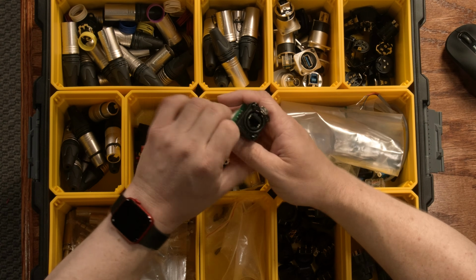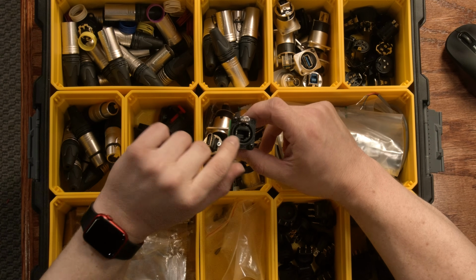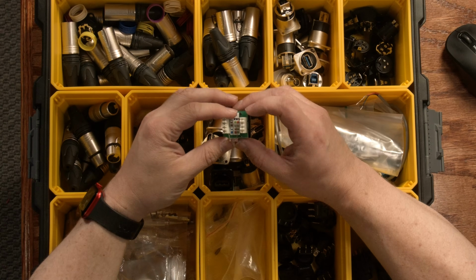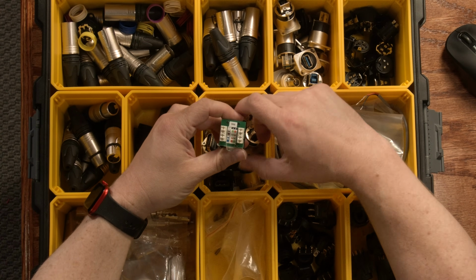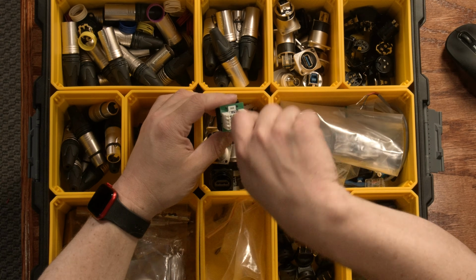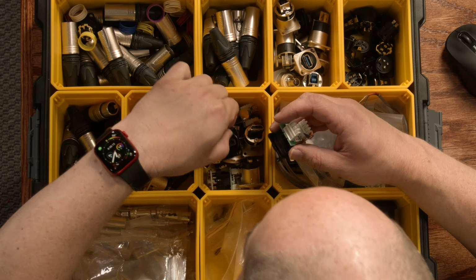Another one that I use a lot is EtherCon, so that's actually an RJ45 for doing Ethernet. And they have a lot of different variations and versions of these too. This is a punch down on the back, so you use a punch down tool to punch it like you would on a patch panel. But they also have feed through versions as well, so you'd have an Ethernet connection on the back that you can plug in there. So what else do I have?